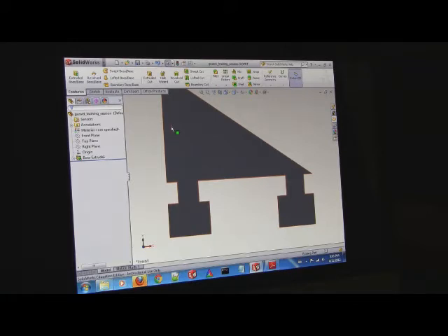Mainly I'm showing you this because it teaches you some of the cool constraints. The ones I'm showing you are the most complicated you want to do. If you start getting much more complicated, it's going to blow up. So has everybody got it extruded with two little thingies? Extrude 19.05. Anyone know what that is in inches? 3/4. An eighth is 3.175, a quarter is 6.35.